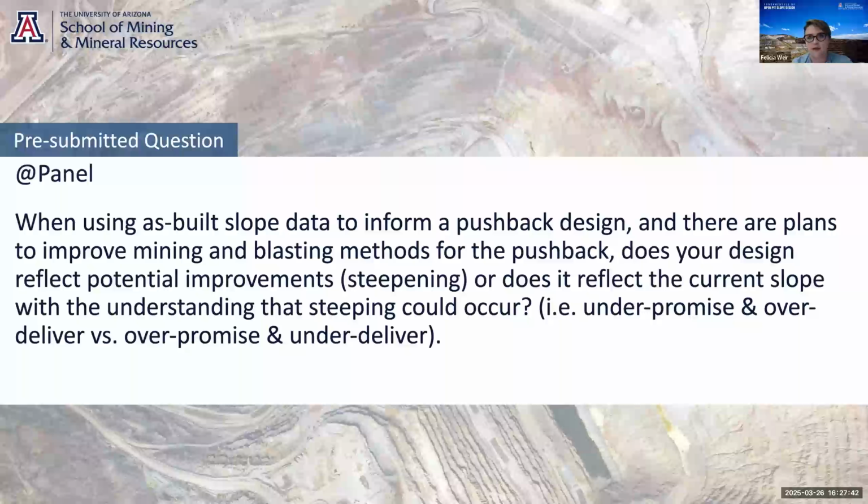Putting things in terms of cost to management can be very helpful. So it's going to cost us this much to put in improved blasting and horizontal drain holes versus the flatter slope design. But I highly recommend some hold points where you've got opportunity to review how the slope performance is going.